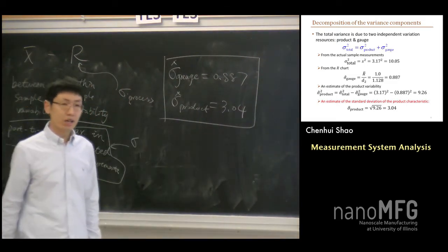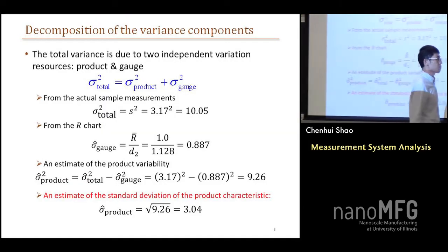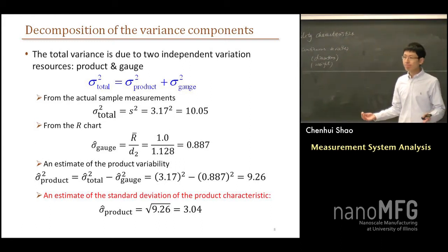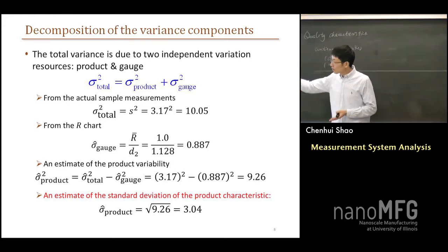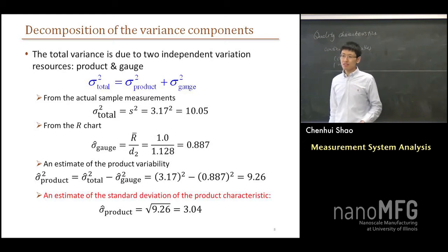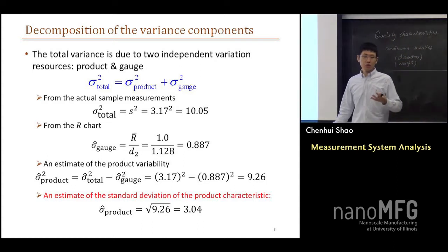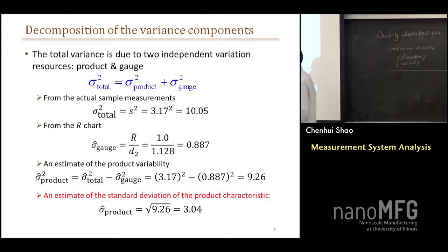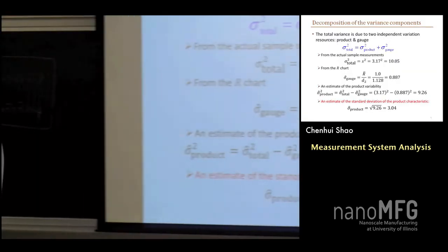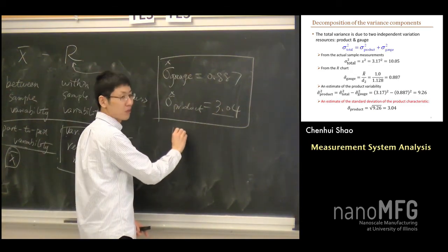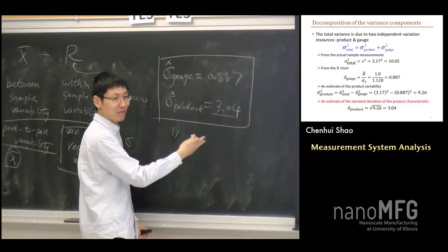Okay, what does this result tell you? Do I have a good gauge? Intuitively, is it good? This point something is a small number, right? And intuitively, it looks not bad. So how about the production process? Do we have a good production line? You don't give me an answer because there's no answer. It depends on your upper and lower specification limits and the 6 sigma, right?